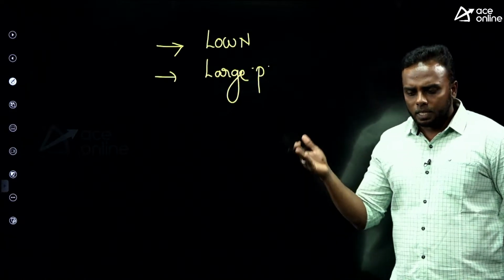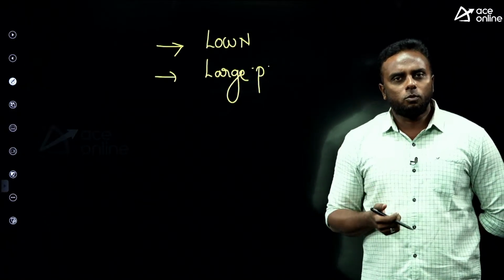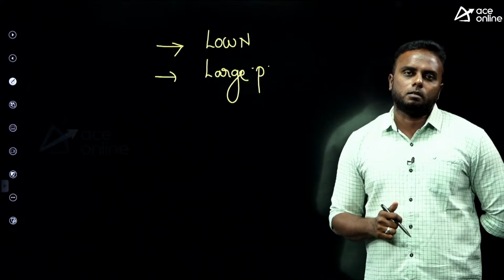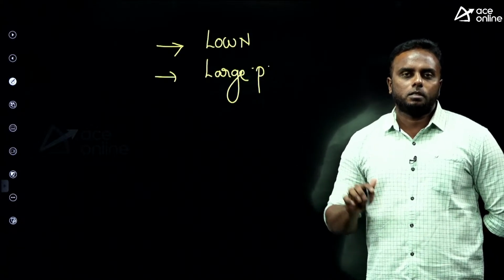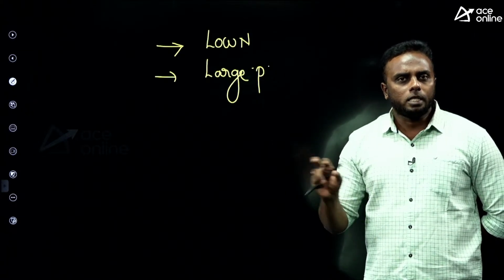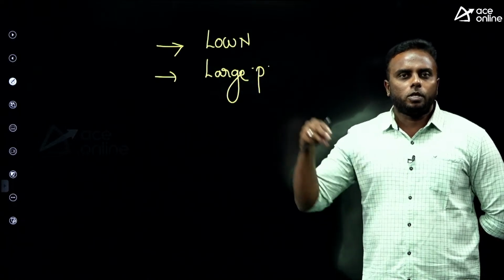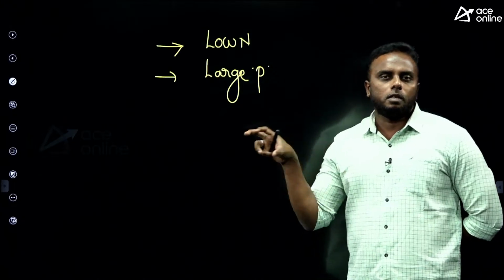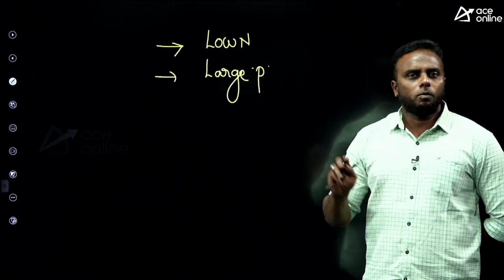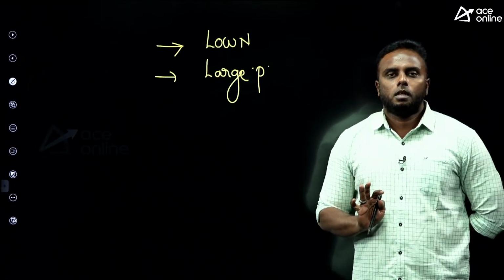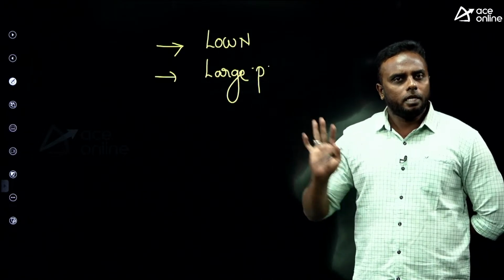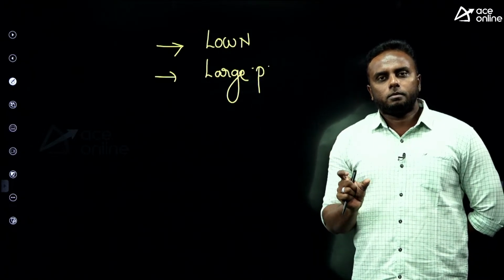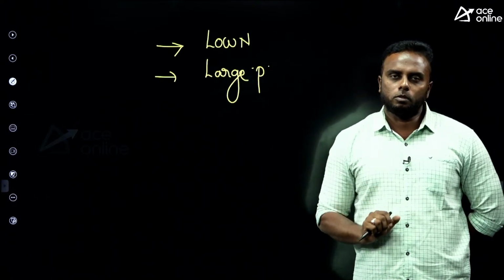Compared to a synchronous motor, an induction motor has less maintenance and less cost, because an induction motor doesn't require two excitations like a synchronous motor. We use stator supply and also DC supply to the rotor field, which is not needed for induction. That's why most of the time we use induction motors, for high speed applications and all. But for low speed, the induction motor is not suitable.